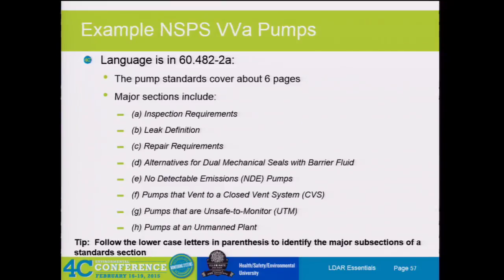Pump standard covers about 6 pages. Major sections include inspection requirements, leak definitions, repair timeframes, alternative dual mechanical seals, barrier fluids, no detectable emissions, so like a magnetic pump. Starting to see more and more of those. They're just simpler, they don't leak.